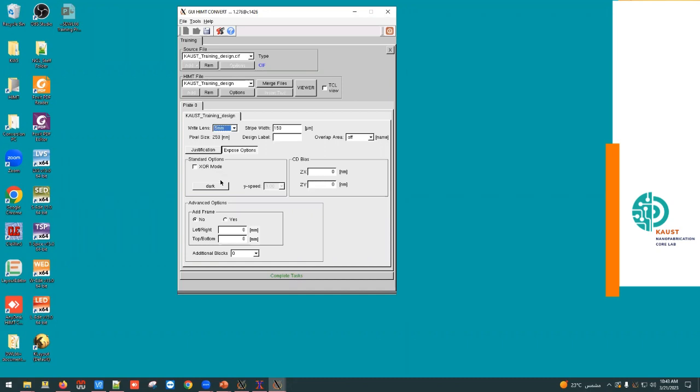So sometimes this option, if you realize that you have one polygon that is enclosed in other polygons, is working. If you click it, it will help you. But my recommendation is just bring one layer and avoid having big polygons enclosing small polygons. Is this clear? Yes. Okay. Yes. Thank you.